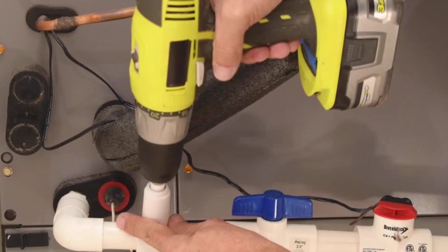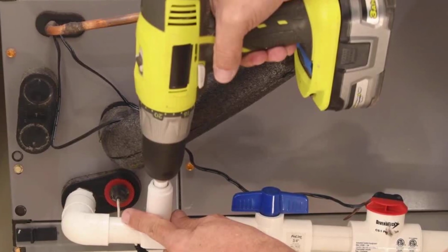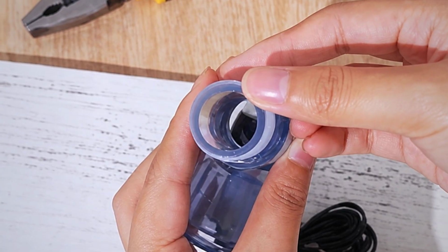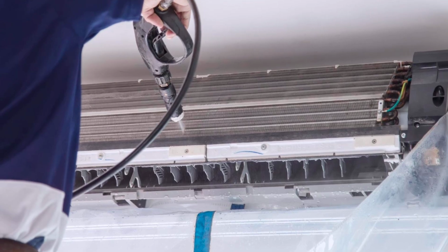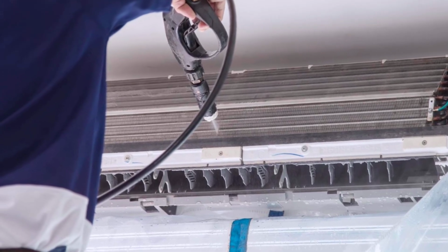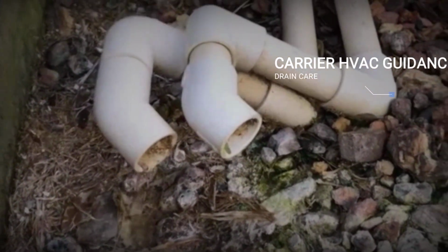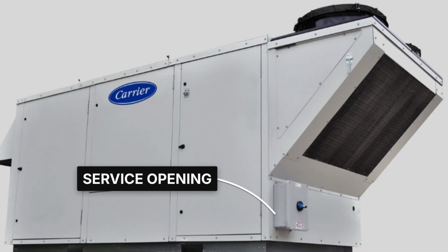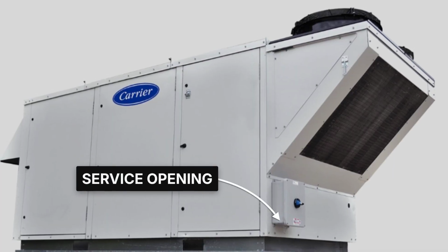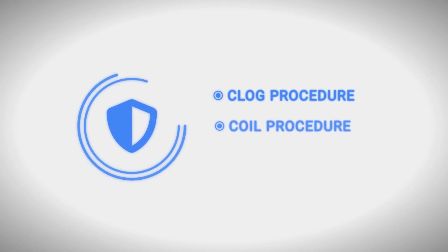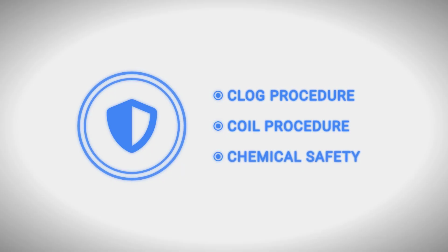That protocol also tells you when the bottle is irrelevant. Standing water points toward clog removal. A tripped float points toward a drainage diagnosis. Dirt on a coil points toward the coil procedure. Unknown residue stops the chemical experiment. Carrier's supported HVAC use is preventive condensate-drain maintenance at the proper access point under the applicable equipment instructions. Use the separate procedures named for clogs, coils, and chemical exposure.